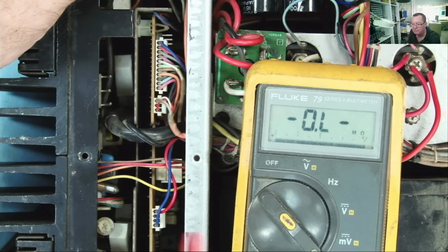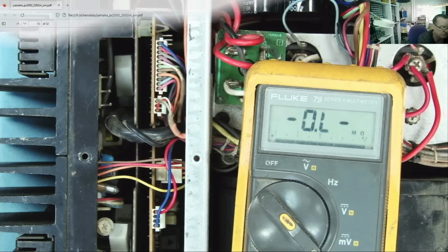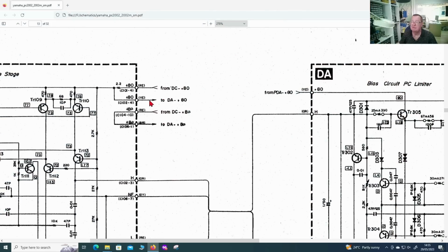And if you noticed on the schematic, and I'm going to show you again what that means. It means the resistance on the yellow to ground is lower than on the red, and look what's in between, a 2.2 ohm resistor. So the fault is here somewhere, but unfortunately we don't know which side because the yellow wire and these all power from this point. Let's disconnect the yellow wire.